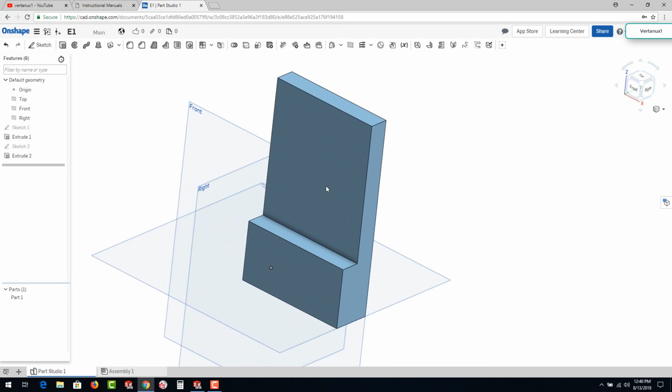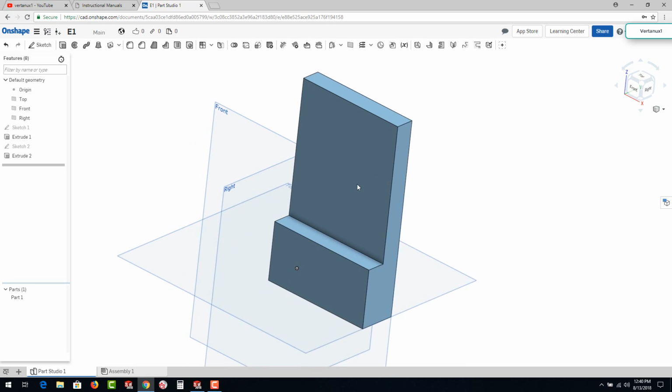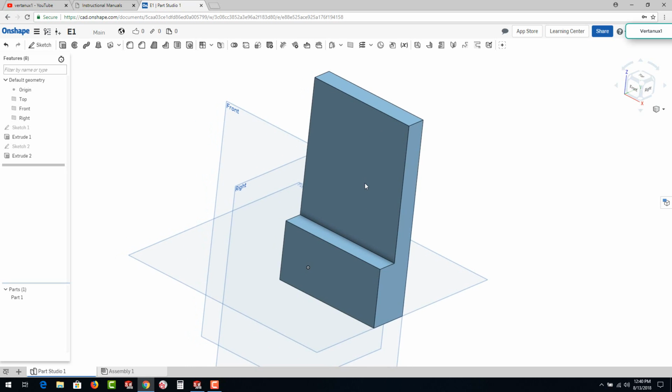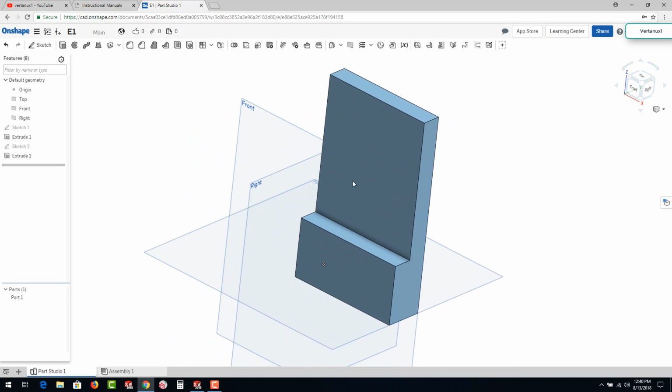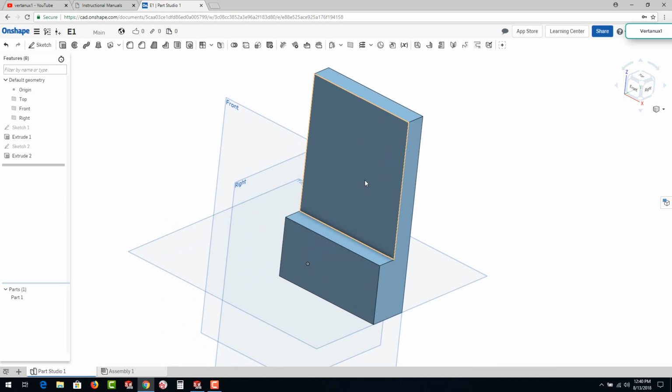If you hold down the middle mouse button, which basically is your wheel, hold it down like it's a button, don't scroll it. We know scrolling zooms in and out. This will pan. Okay. So there's just a few samples. There's a lot of other options for that I'm not going to go into right now.